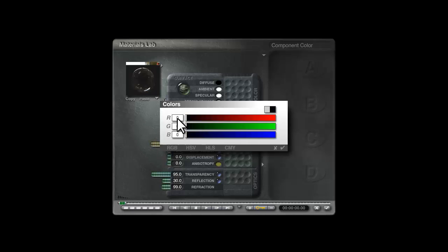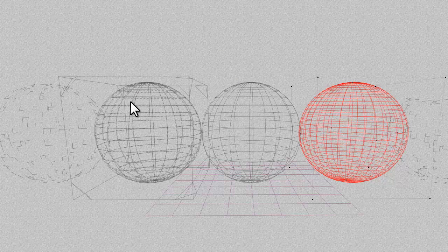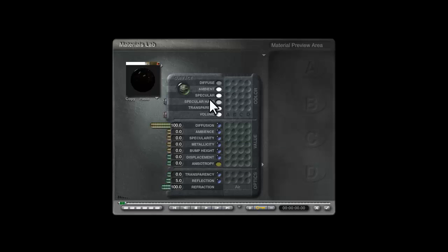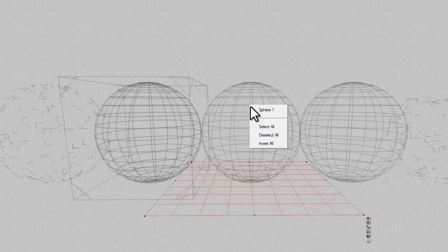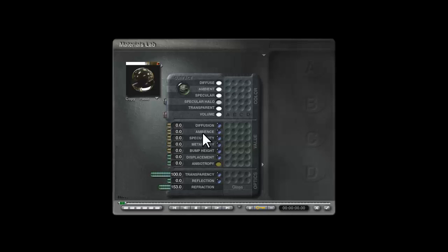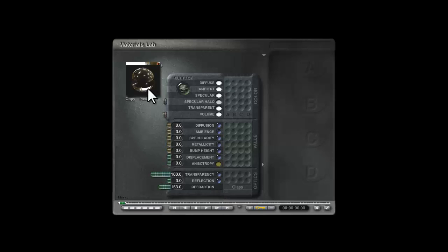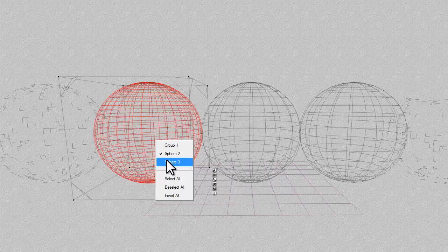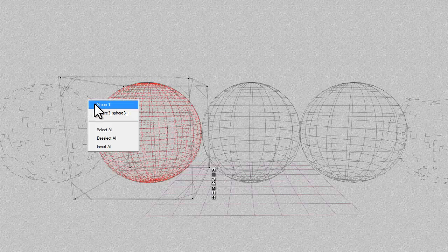So we want it to be set fully black for ones we want sharp reflections on, and then at a higher value. So the default value here might be appropriate for this, because that's going to be a bit blurred there. So let's go through all our materials now and modify the specular halo. Right, want the sphere 2, so specular halo there and there. So that's that fully black, and then we can use blurred reflections.